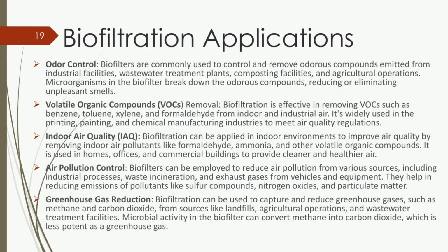They help in reducing emissions of pollutants like sulfur compounds, nitrogen oxides, and particulate matter. Greenhouse gas reduction. Biofiltration can be used to capture and reduce greenhouse gases such as methane and carbon dioxide from sources like landfills, agricultural operations, and wastewater treatment facilities. Microbial activity in the biofilter can convert methane into carbon dioxide, which is less potent as a greenhouse gas.